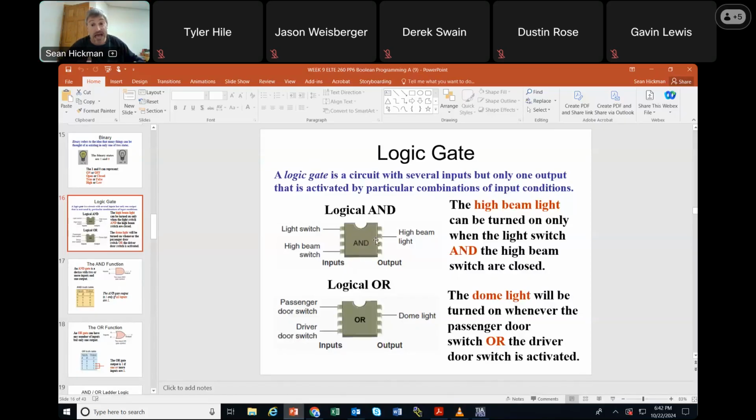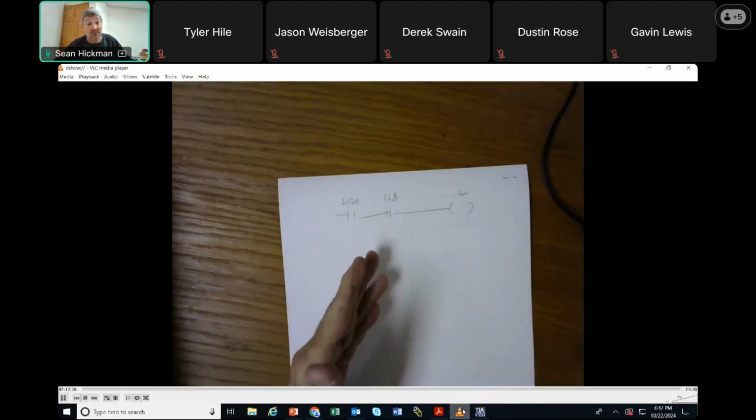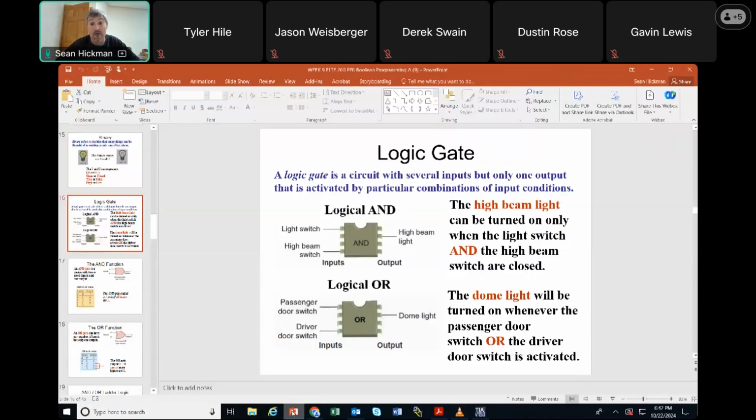Well, it's not. Ladder logic is not the way things are programmed. It's just a way of presenting logic. This box right here, that's an AND, and you've been trained in your mind to see it as ladder logic. But if you're a straight coder, somebody who's just a computer programmer, they've never seen ladder logic. We just kind of made it available to you. What's going on inside of here? Yeah, this is kind of going on inside of there, but it's just logic. It's not actually ladder logic.